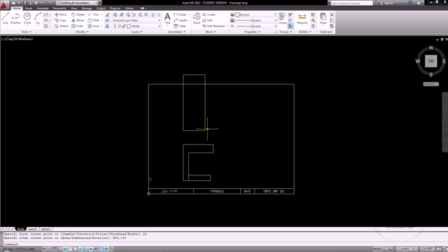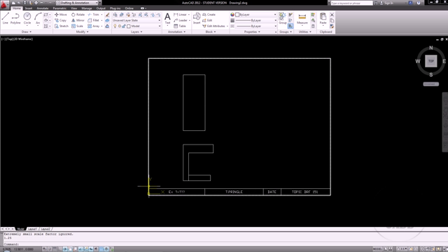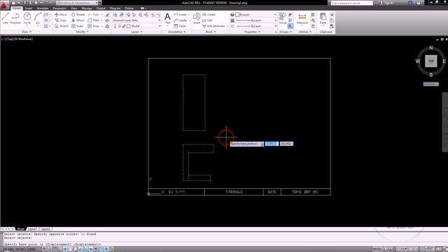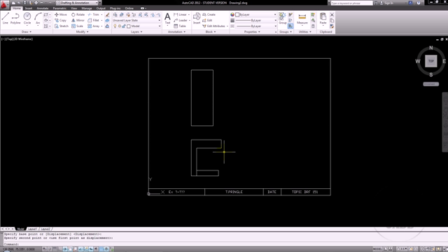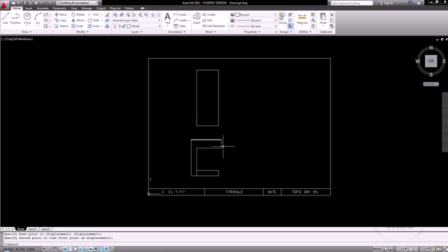and you can see that that does go off of the sheet a little bit. On this particular exercise, what we're probably going to want to do is go ahead and scale up the title block, and just the title block. So you see I've selected everything in the title block using the scale command, which is right here. And I will pick right here as my base point and just type 1.25. And what that's going to give us is a title block that's scaled up 1.25 from what it normally would be. So now I can move this so that it lines up right here, which is where that bottom piece actually